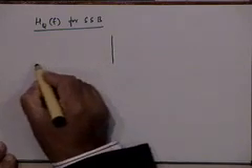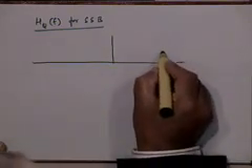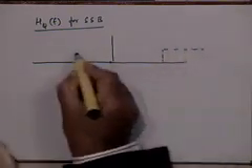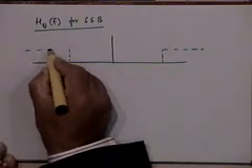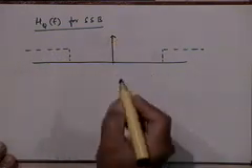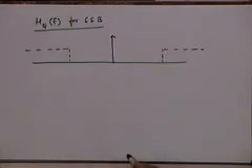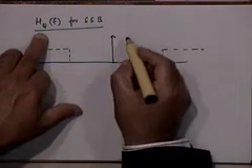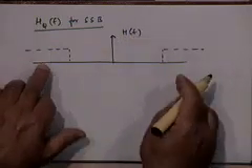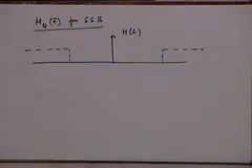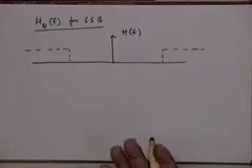For an SSB signal, what is your transfer function? It is like this. Basically what do we hope to see? That if we derive HQF from H of F using the condition that we have just discussed, we must get the Hilbert transformer, because we know that is how the quadrature component of SSB is generated, through Hilbert transformation of MT. So HQF should turn out to be the Hilbert transformer. Let's see whether it does.